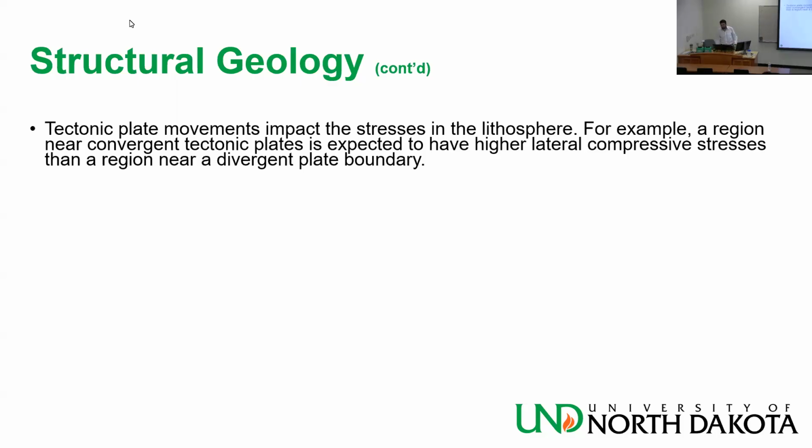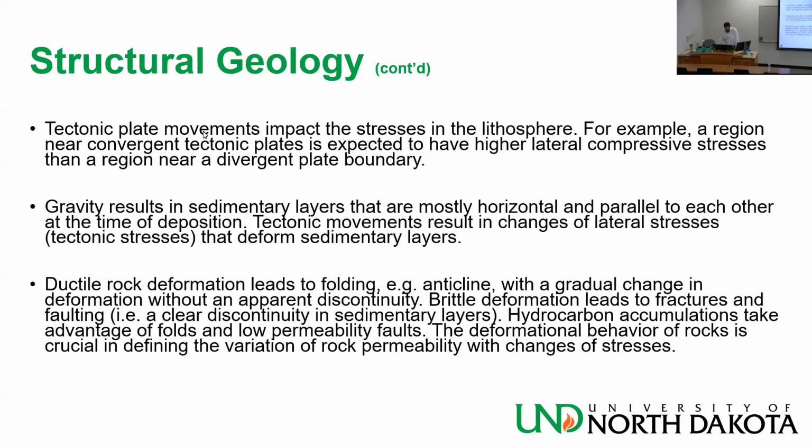Tectonic movement induces stresses, and gravity has a lot of impact. The way the rock behaves, its ductility and brittleness, are not exactly antonyms. They are antonyms in the English language, but technically, low ductility doesn't necessarily mean brittleness.